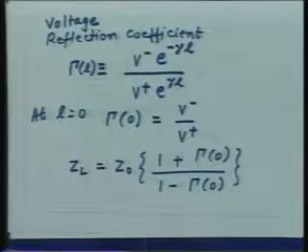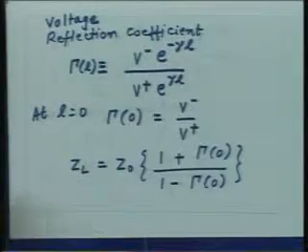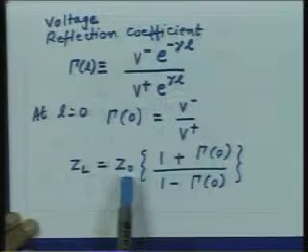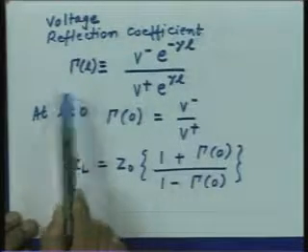Ideally, if my intention is to deliver the whole energy to the load, this quantity should be as small as possible. In the next lecture, we will establish the conditions under which you will have full transfer of power to the load, or no reflection from the line. Also, we will briefly discuss why there is a reflection on the line, what the reflection coefficient essentially indicates, what the role of the load impedance ZL is, and what the role of the characteristic impedance is in reflecting the energy from the load and the transmission line.